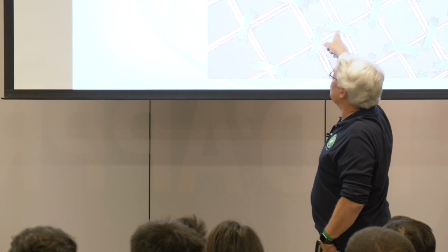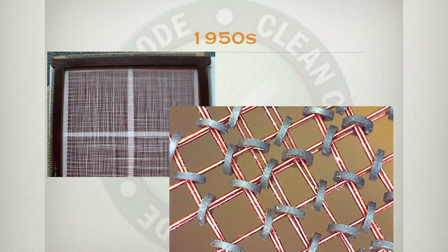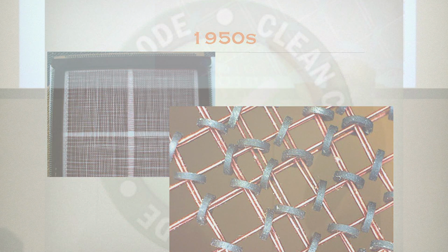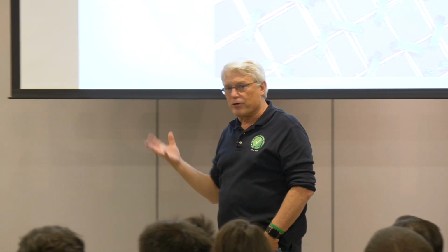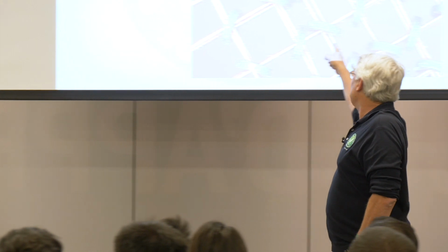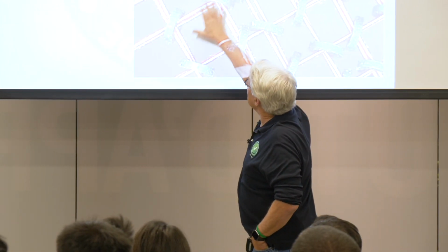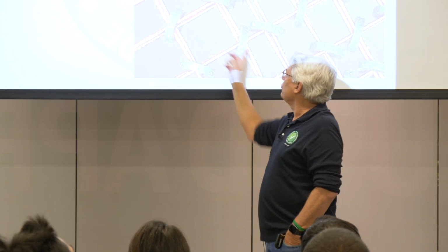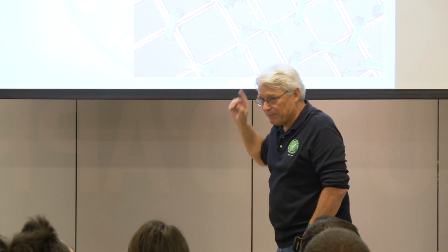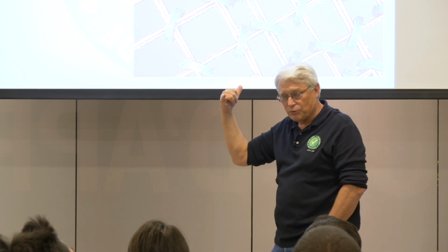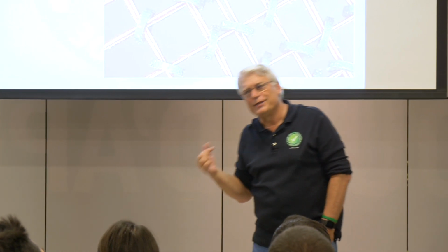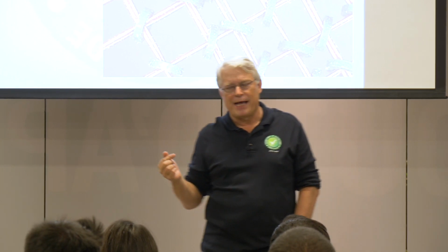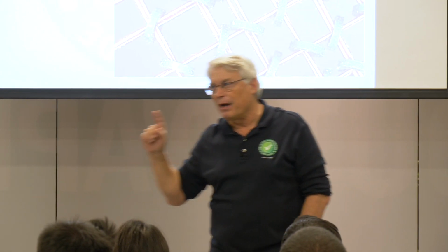This is a micrograph of the same structure. I took this micrograph. This is a core plane. These little rings are ferrite. Ferrite is powdered iron and clay that has been baked. Now, it's powdered iron, so it's magnetic, and it's clay so that you can get this shape, and then you weave them into this network of wires. Now, why? Well, if you run just the right amount of current through these wires, you can magnetize one of the rings. If you run too little current through the wires, the rings don't magnetize. But if you run just the right amount through, they do.